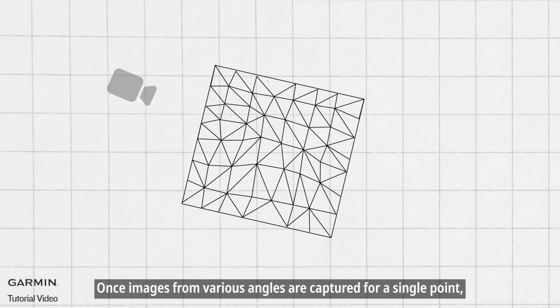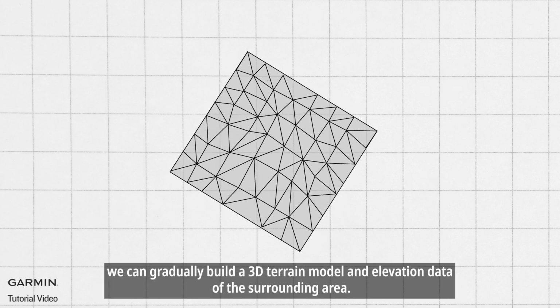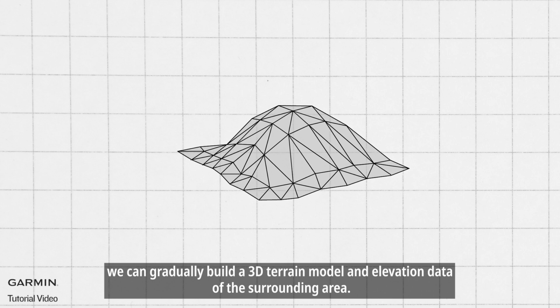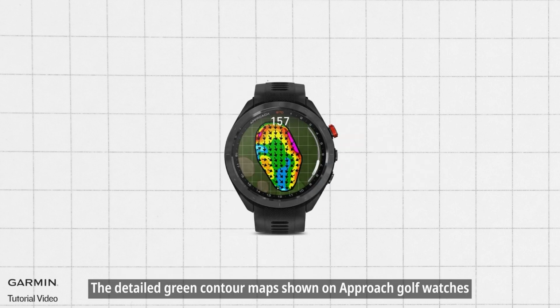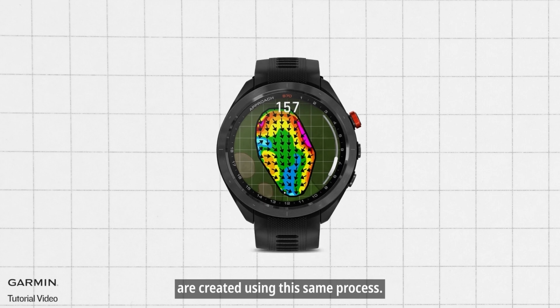Once images from various angles are captured for a single point, using triangulation, we can gradually build a 3D terrain model and elevation data of the surrounding area. The detailed green contour maps shown on approach golf watches are created using this same process.